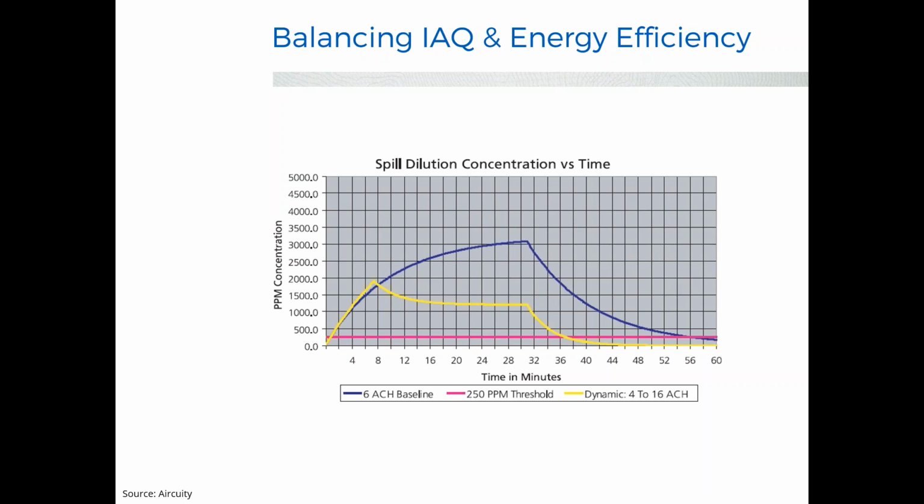I can't say which organization or facility it was, but basically they were looking at implementing demand controlled ventilation with the air acuity system. So basically installing a number of sensors within the facility to measure the concentration of different indoor pollutants at these different areas.